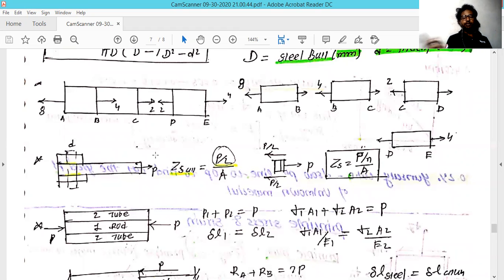So now come to the fourth section, which is D to E. If you draw the vertical line, you need not vary with respect to the entire cross section from A to D. You just simply take the force which is acting in the E direction, which is also tensile in nature, going in the outward direction. If you calculate in a different manner as well, you will find the same answer, which is nothing but 4 kilonewton in the tensile direction. So this is how you can find out the example.